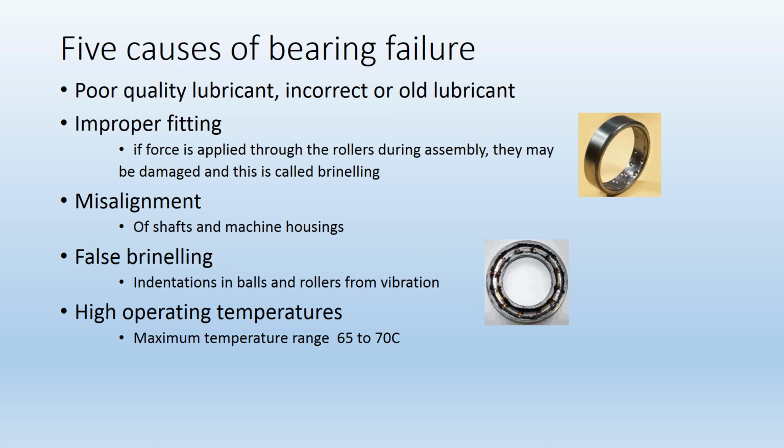The last cause of bearing failure is high operating temperatures. The maximum temperature range that we want to have a bearing generally go up to, the highest, 65 to 70 degrees Celsius. That should be the highest unless you have a special application.